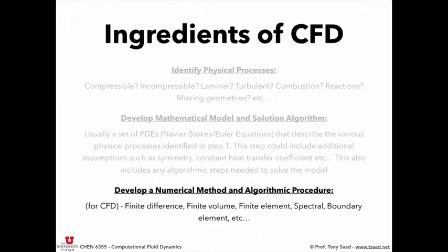Finite volume is the most popular, and we will end up doing finite volume methods in this class, but we'll start with finite differences. Unfortunately, we won't cover finite element methods. There's a course in mechanical engineering for finite elements, but there are other methods like spectral methods, boundary element methods, control volume, finite element based methods, all of these complex methods, but they all share similar features. In the end, what changes is the way you are approximating your unknowns on the discrete grid.